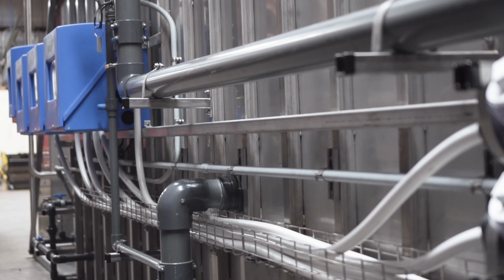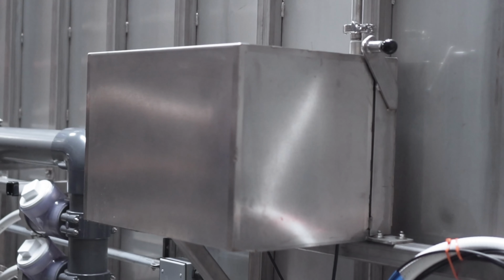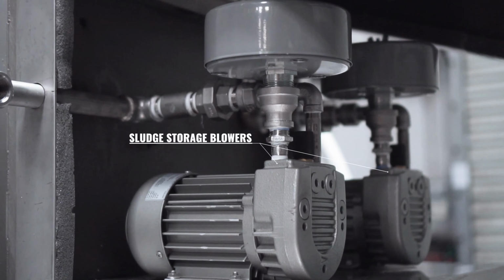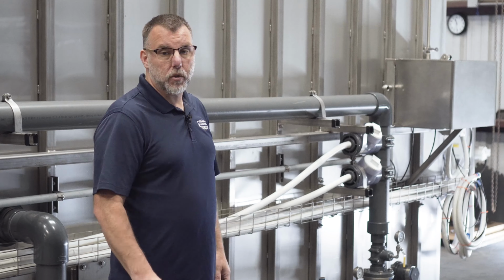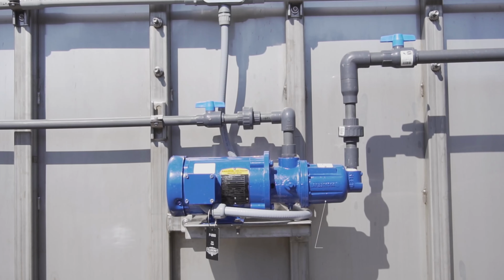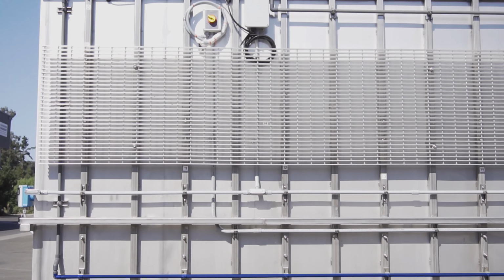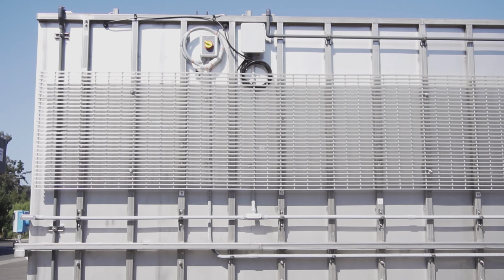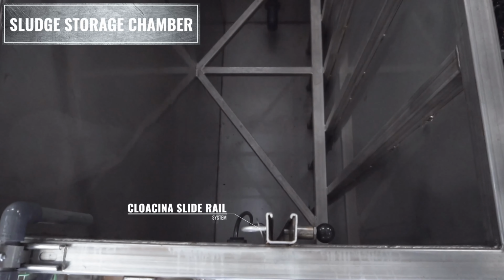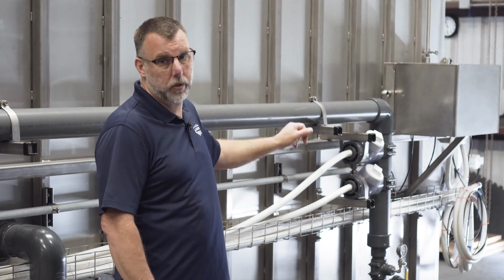At the end down here, we have an integrated recirculation pump for the primary process, as well as a small blower for the integrated sludge storage chamber. So from the secondary process, we are monitoring the mixed liquor suspended solids, and we are automatically pulling waste activated sludge and discharging it into a monitored integrated sludge storage chamber that is aerated to ensure that the sludge remains fresh and we get no odors from this system.